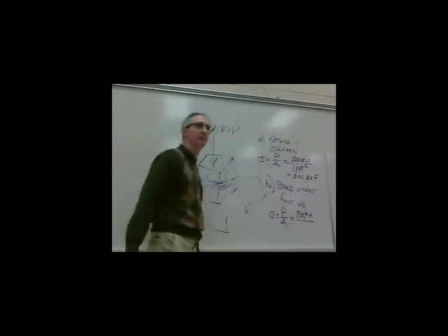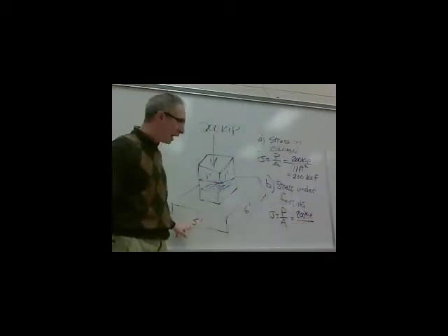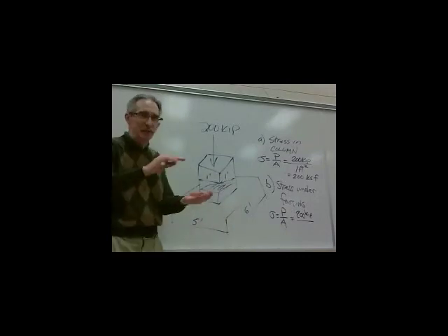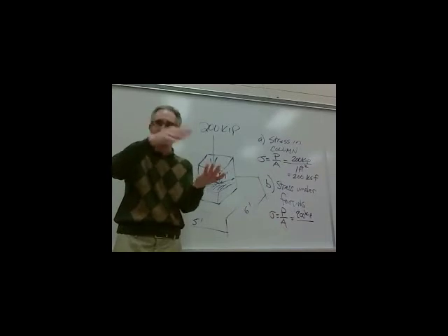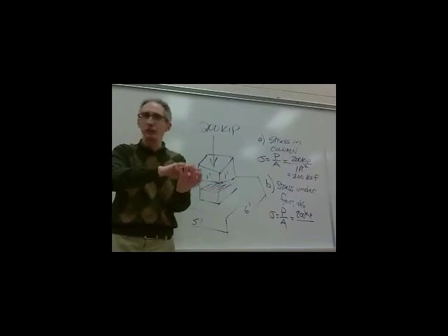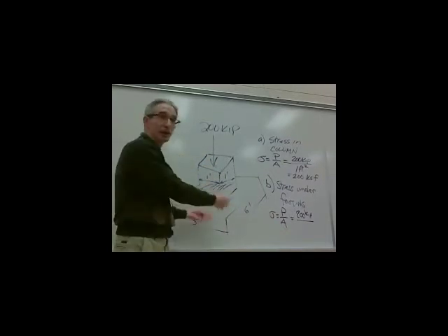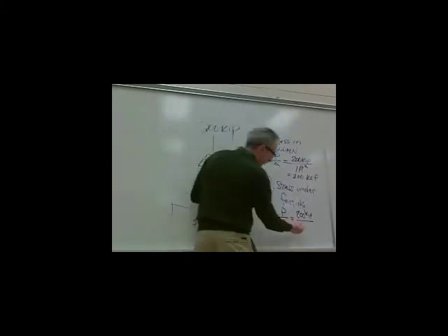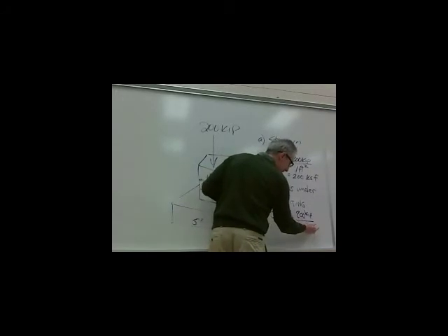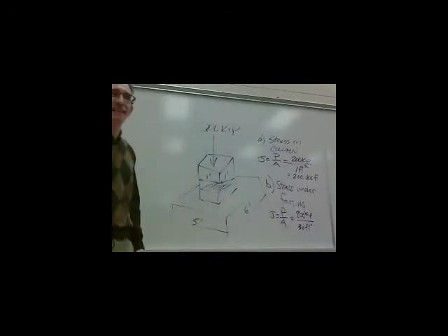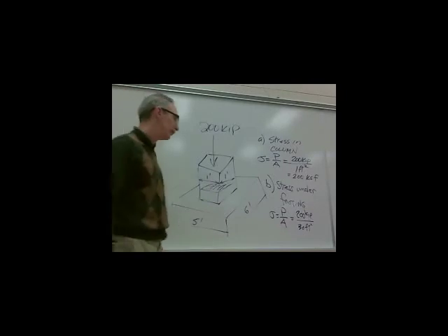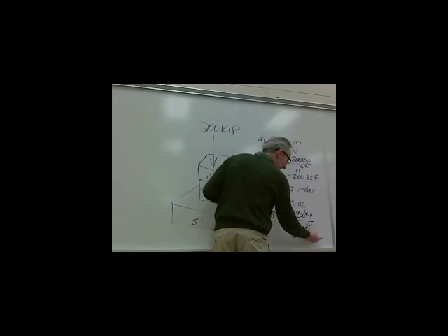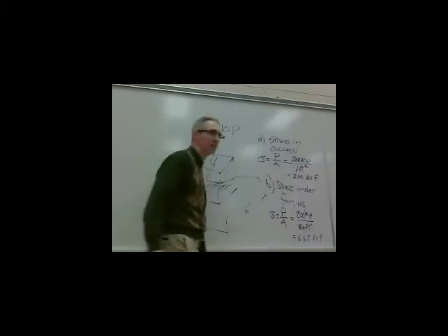What's the area? 5 by 6. It's that rectangular cross section. In bearing, it's the actual cross section of whatever it is. In this case, the footing that's bearing on the lower strata, which might be soil or whatever it is. So in this case, that's 30 square feet, 5 by 6. What's 200 divided by 30? 6.67, again, in units, kips per square foot.